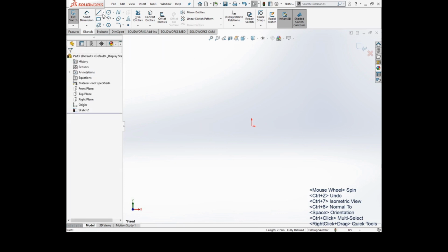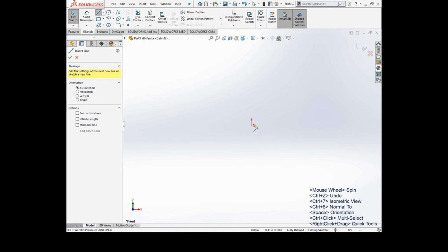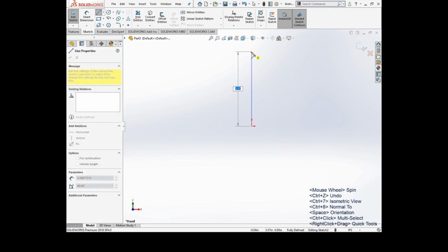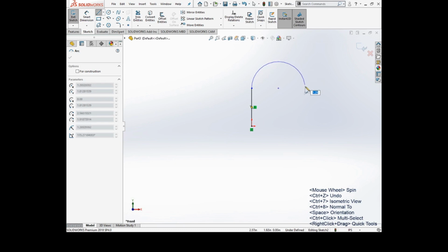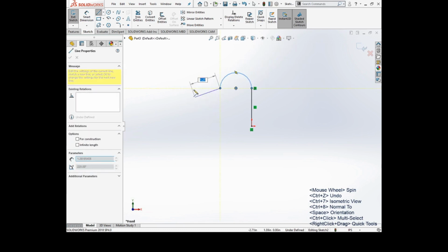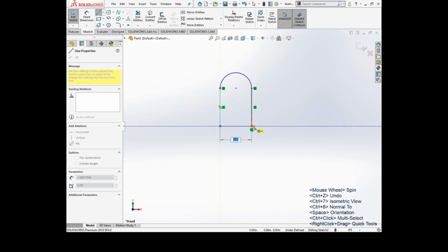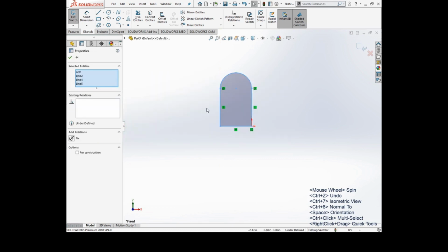Okay. So the second line, well, actually, there's one more thing with the line tool you can do. You can drag it out, create your line, and then you go out, bring it back in, and then drag it out, and you will now get a tangent arc tool. So you can make your tangent arc, and then it goes back to the normal line tool. So you can make a nice little, I don't know, tombstone looking thing right there with that.